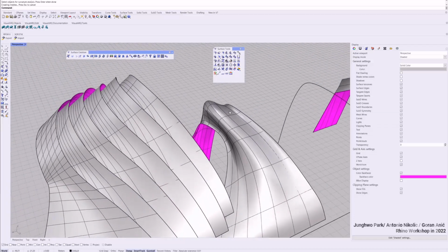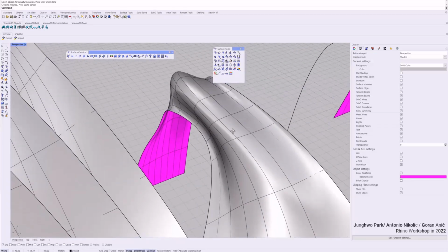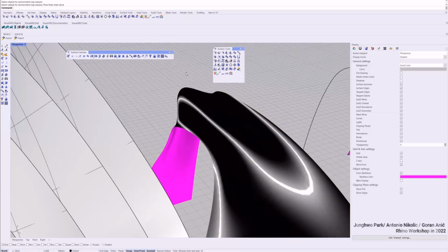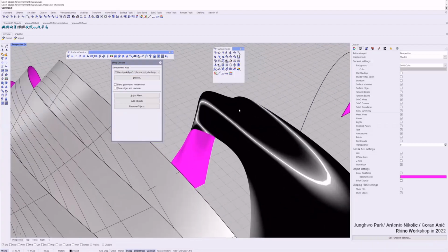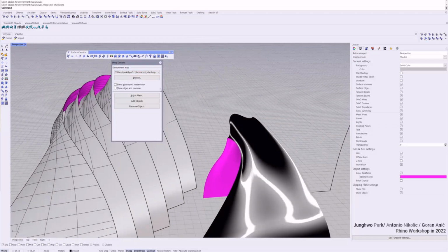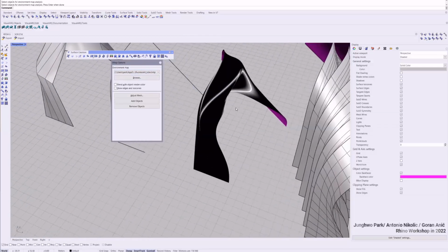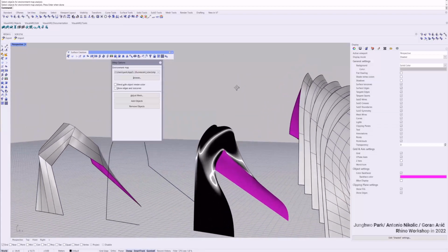And if you want to check the reflection of this surface prototype, then you can go here, surface tool, and when you look at the environmental map, you can turn it on for this surface, and you can choose what kind of environmental map you want to provide. You can see here, when you do fluorescent map, you can see the reflection of the surface, how it will reflect.